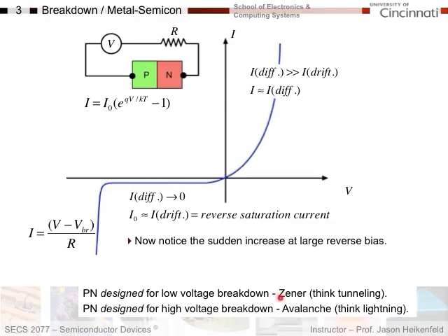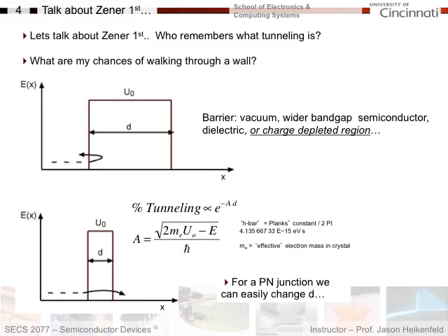And this is done by Zener Breakdown, which is related to tunneling. The type that is the puff of smoke type is at higher voltages typically, and that's Avalanche Breakdown. Think lightning bolts, okay? And that's far more destructive. So let's look at both types of breakdown today. So let's first talk about Zener Breakdown.